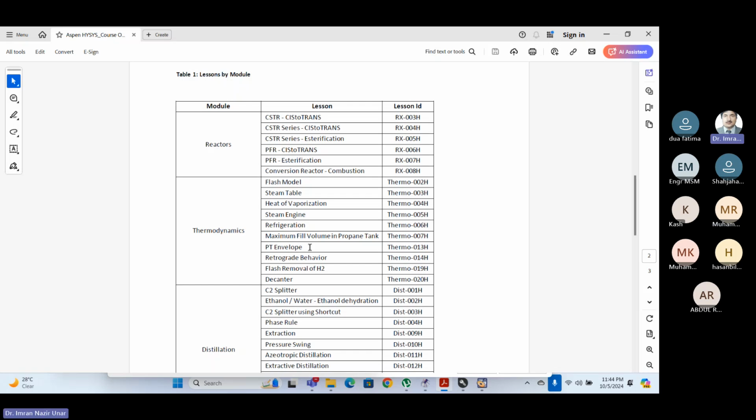I want to give you one overview regarding thermodynamics. You know that in thermodynamics three things are very important. One is called the state variables. We can say that temperature and pressure are the state variables of any substance or material. When you fix the pressure and temperature, then its volume and its phase are accordingly fixed. So basically, the PVT behavior is very important, and this is the sole thing which we as chemical engineers learn in thermodynamics.